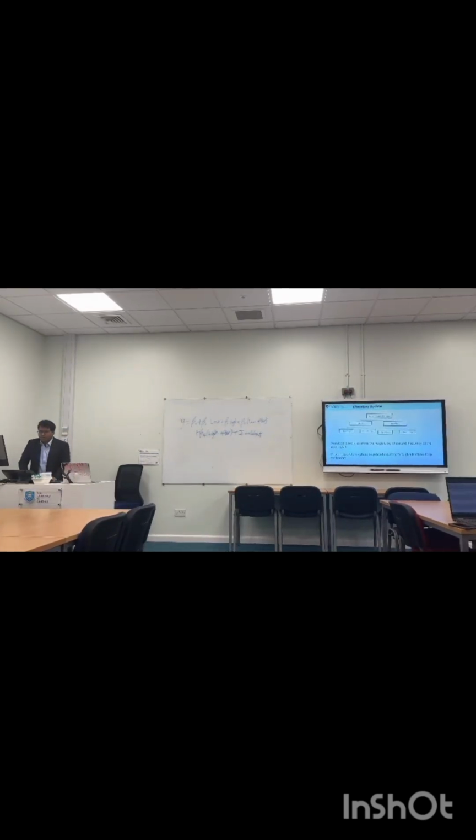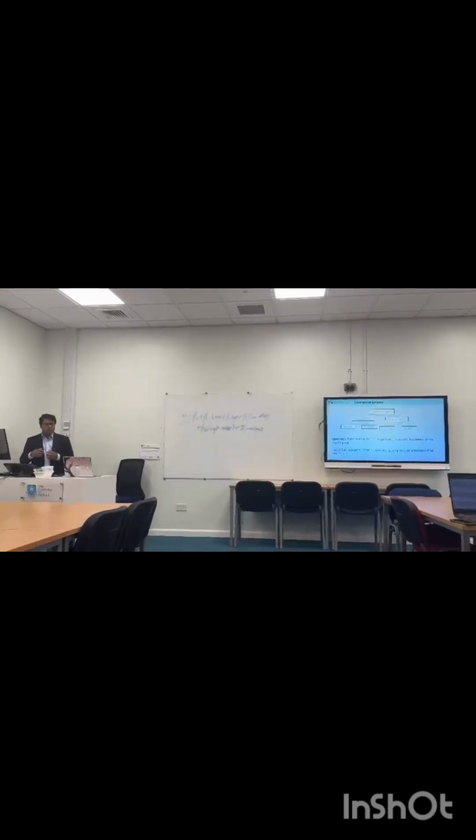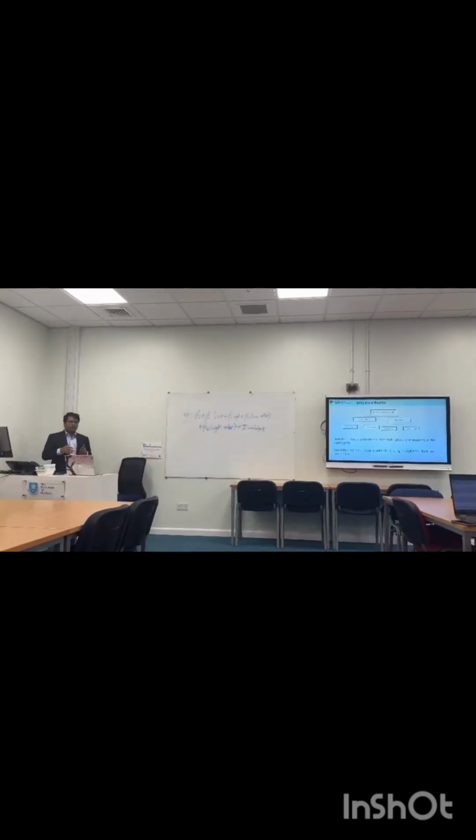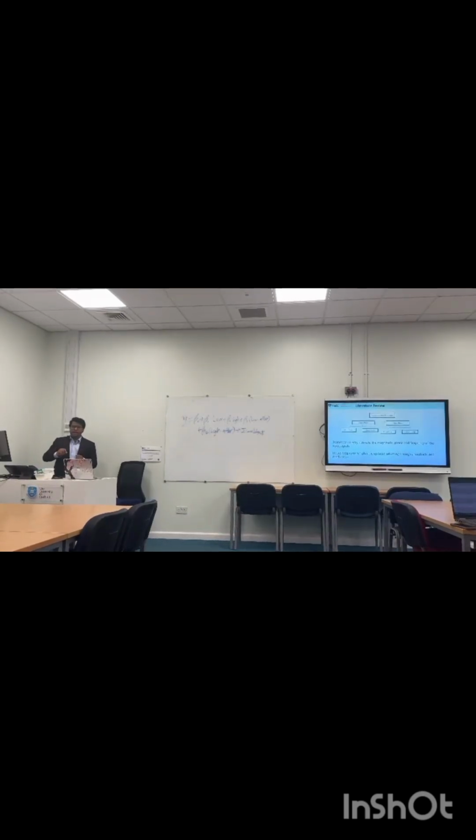In the literature review, I went through several researches, and research is ongoing on this topic. In synchronization, there are two main methods: the open loop method and the closed loop method. In the open loop method, they estimate the phase and frequency directly. In the closed loop method, there is a PLL, called a phase locked loop. It is feedback control, and the angle is corrected after every loop, because the phase is adjusted through a feedback loop.